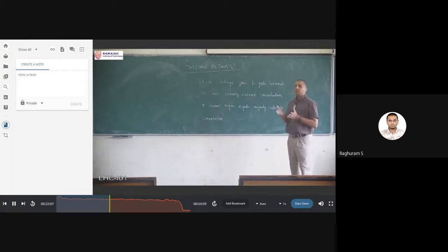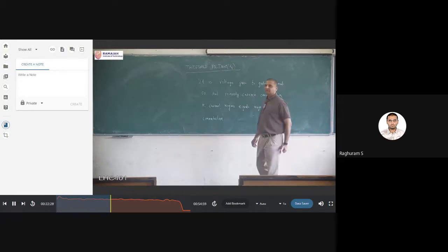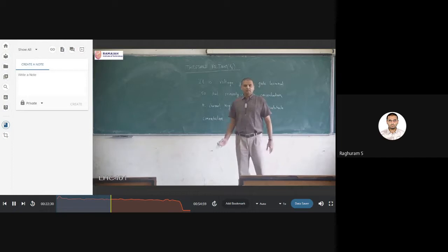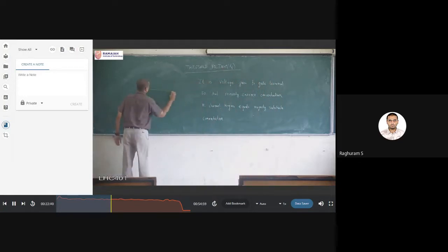Now we are talking about these modes of operation. We have accumulation mode, that is completely useless. We cannot have any current conduction. We have depletion mode, that is also not very useful. We have inversion mode. Now inversion mode is the one that is interesting to us because here the transistor is on. Now the question that you might ask is, how on is on, right? It's not like a perfect thing saying how many electrons should be attracted to the channel region. So if I redraw this diagram,